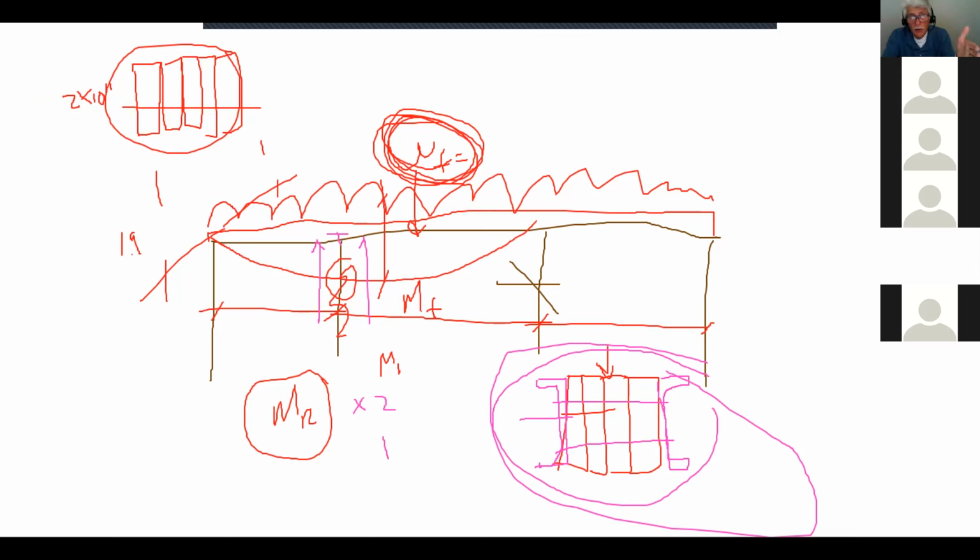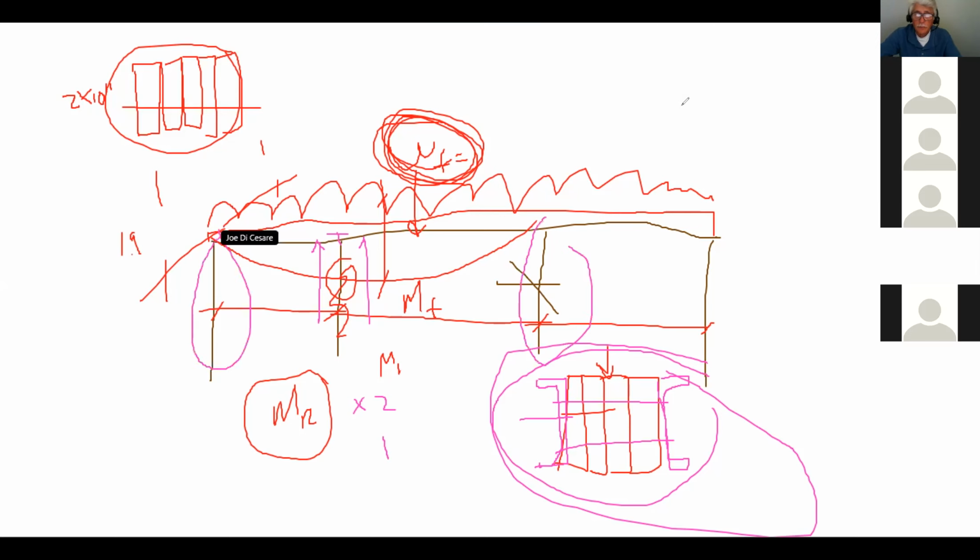So the drawings are the first thing, then after the drawings, the loads, after loads, the analysis. Once the analysis is done, then we can look at our options for additional reinforcement. And you might have to reinforce this column here, because there are more loads going onto that column.